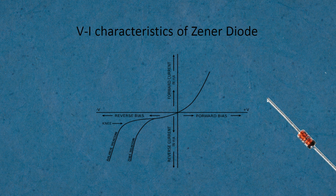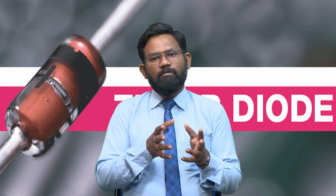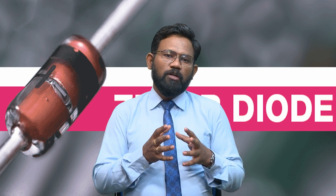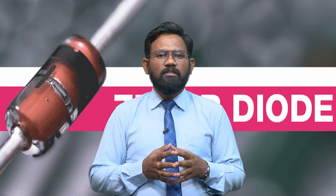A particular point occurs where the avalanche breakdown occurs. The Zener breakdown occurs before the avalanche breakdown, and as we have studied, the condition for that is that the amount of doping is increased. If the doping is increased, we can obtain the breakdown before the avalanche breakdown, and that is called the Zener breakdown. In this way, the two types of breakdowns are different from each other. This VI characteristic shows the two types of breakdowns in the reverse bias region, and in the forward bias region it works similar to a PN junction diode.